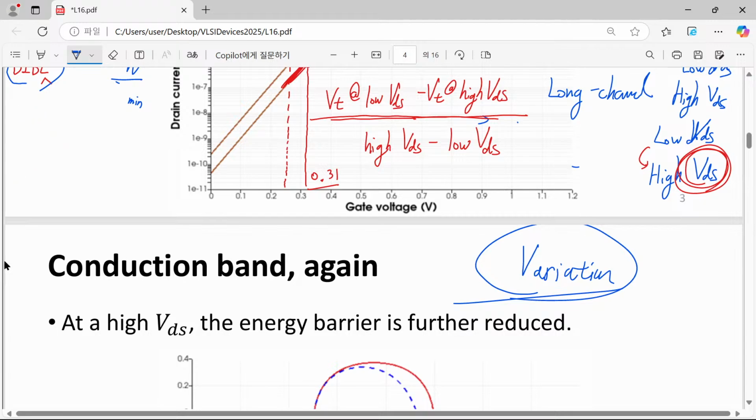Up to now, the history of technology scaling is like this. Well, we wanted to reduce something. For the next generation technology, we invented a way to control DIBL. Since DIBL was controlled, our Ion was increased.